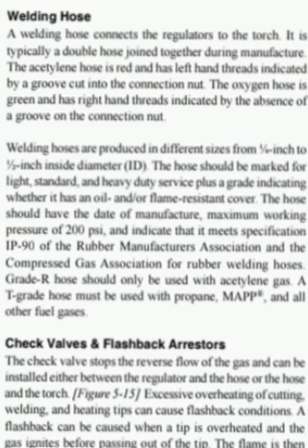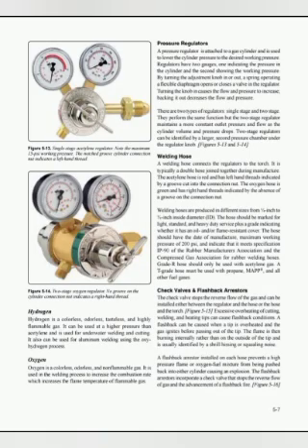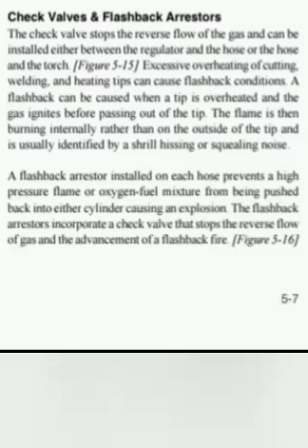Excessive overheating of cutting, welding, and heating tips can cause flashback conditions. A flashback can be caused when a tip is overheated and the gas ignites before passing out of the tip. The flame is then burning internally rather than on the outside of the tip and is usually identified by a shrill hissing or squealing noise.